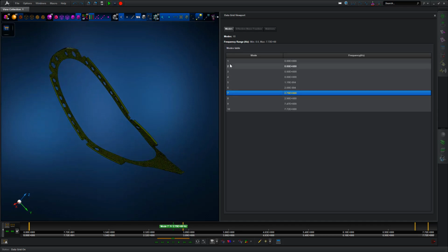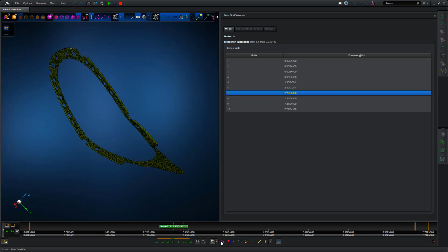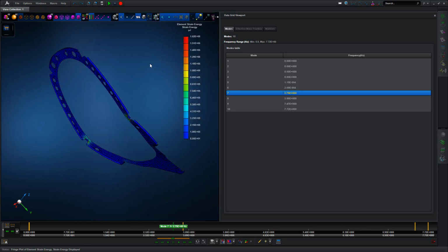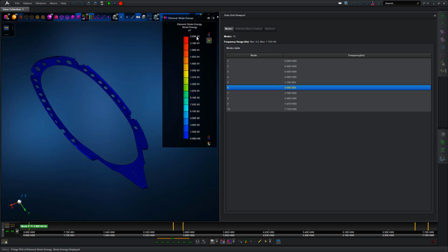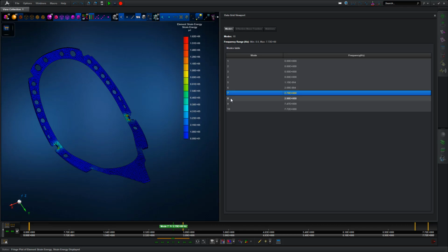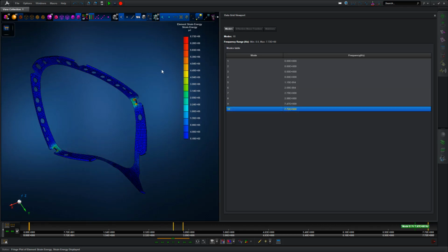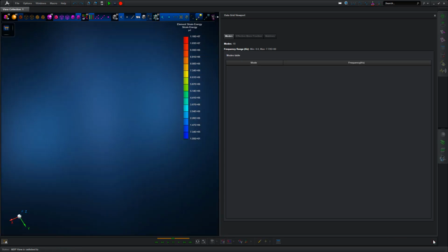We can look at fringe plots in terms of deformation and/or strain energy to allow us to assess what's going on. So we turn the fringe plot on and switch to strain energy, and we can see the 7th mode, which is the first elastic mode again, shows a sort of hinging effect where we've got a lack of stiffener in the overall model, and we can cycle through each discrete mode and make sense of the model response.